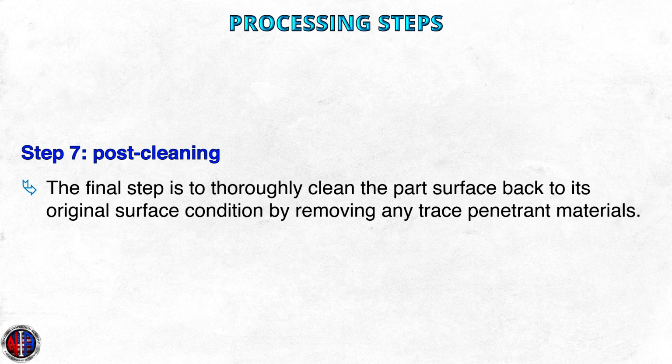Step 7. Post-cleaning. The final step is to thoroughly clean the part surface back to its original surface condition by removing any trace penetrant materials and especially the developer. Developers remaining on the surface tend to wick moisture from the air and can accelerate corrosion on the part.